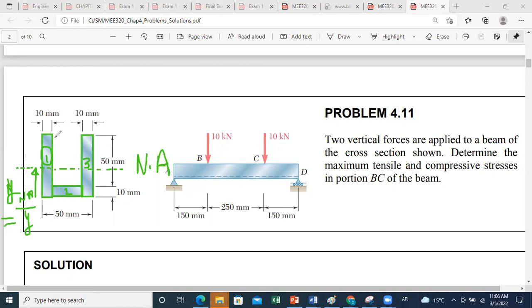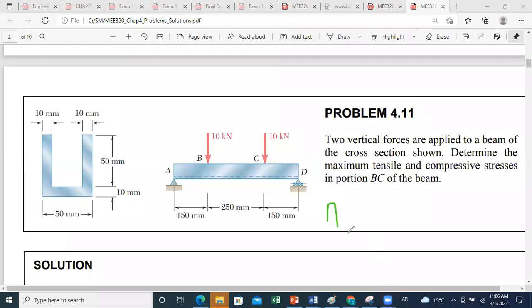Okay, to do so, I will use a table. If you remember from statics, what is the method to find the centroid location? I need to use a formula. The formula is total area times y bar, or centroid coordinate, equals the sum of a_i y_i.